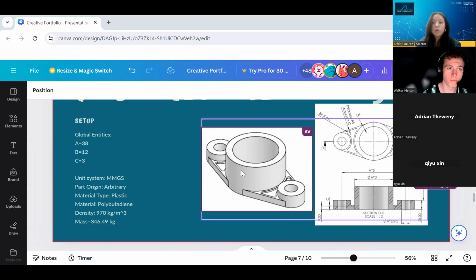Jonathan, to change units, you want to look at the bottom right corner. It should say IPS. If your SolidWorks is set up like that, click on it and it should show you all the options to change. Let me know if that worked for you.